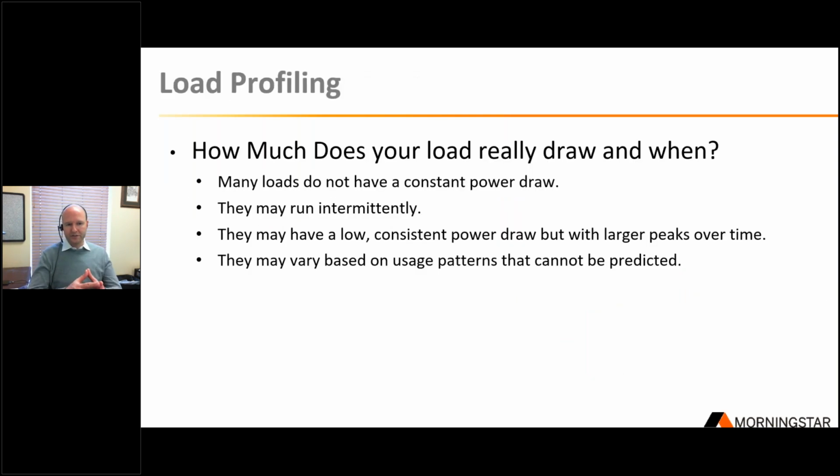So the next thing I wanted to talk about is understanding what your load really draws and when it draws it, because this also is important for design. I've seen a lot of customers surprised with the equipment they want to power, looking at it from a 24/7 standpoint. It's not consistently drawing the same amount of power. It may draw more when it's doing more computing or processing or transmitting. There could be things that turn on and off within the system that they're not aware of. So you want to look at the intermittent properties of the load. You may want to look at if they have a high surge. It can vary a lot based on the usage patterns of the system.